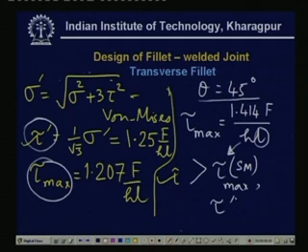Now, this is normally used in practice. Although this is almost a thumb rule and in no way an accurate theoretical result, of course, it is very useful, and this is called the unified formula. So, let me write down this formula again, which will be the basis of calculations for the strength of a welded joint for a transverse fillet weld.